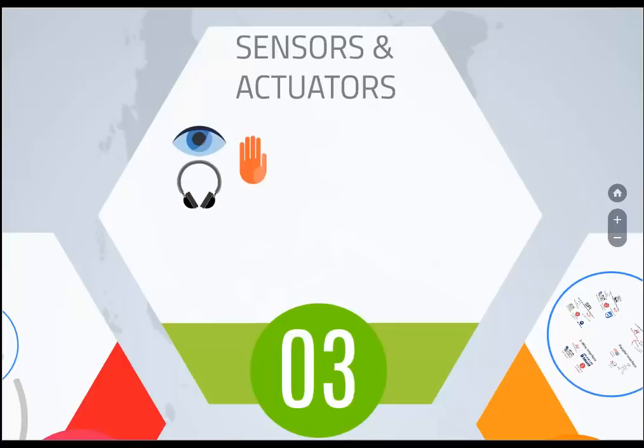A sensor, by definition, is a transducer device that converts energy from one form to another for any measurement or control purpose. And an actuator is a form of transducer device, mechanical or electrical, which converts signals to corresponding physical actions, that is generally motion. An actuator acts as an output device. At a later stage, we'll discuss in detail different kinds of sensors and actuators. But just in brief, we'll see a few of them here.